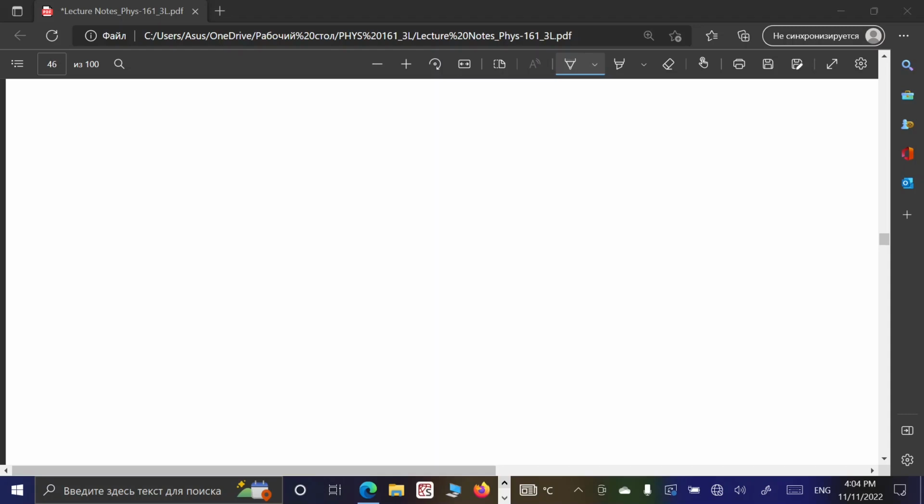So what can you tell about unique properties of freon as a working medium with this heat pump? Its temperature is highly dependent on pressure. Opposite, boiling pressure is strongly dependent on temperature, and that is the key requirement, because otherwise we will not be able to realize this technically.